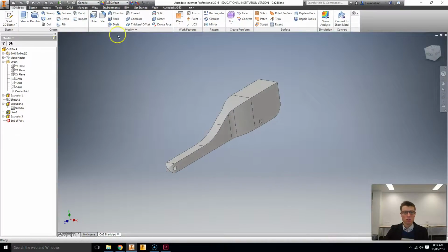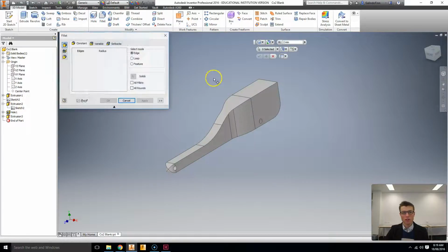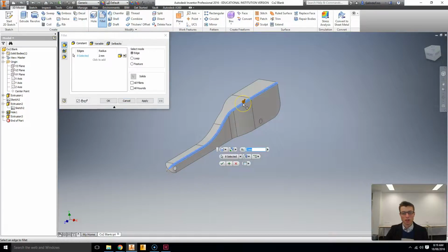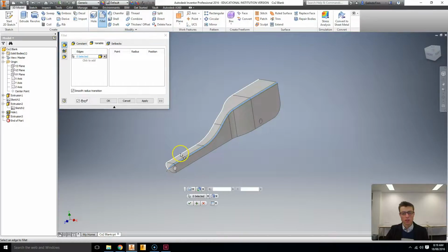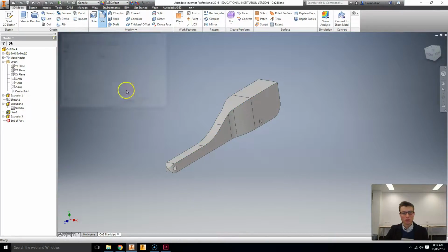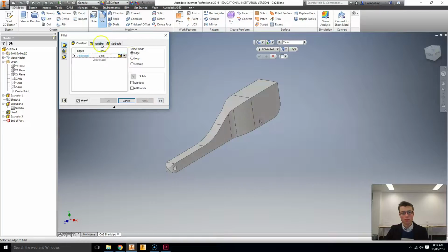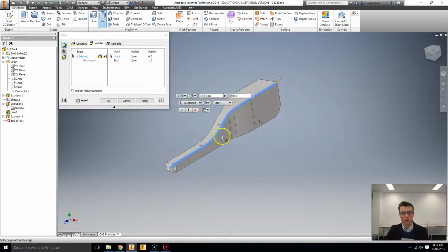But you could also do some visual aesthetics. So if I click the fillet tool and select this line here, I could select a variable fillet, and then selecting the edge, I could change the radius at the end, say to 10, and the radius at the beginning leaving it 0, and you can see how the fillet gets wider the further back you go.